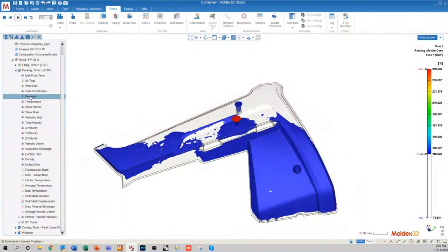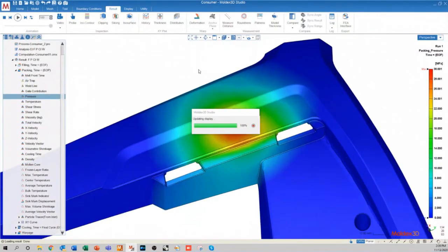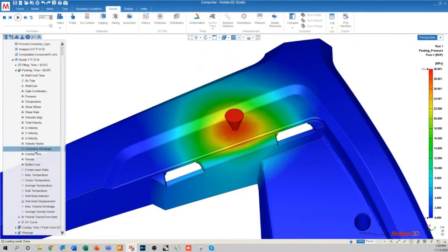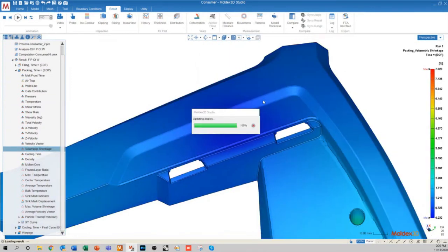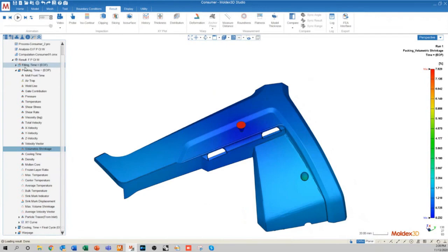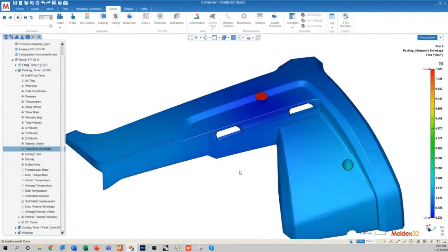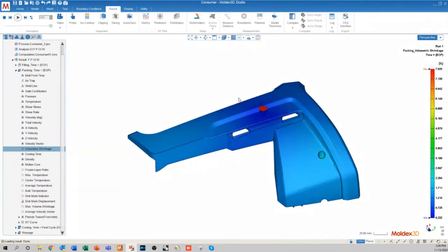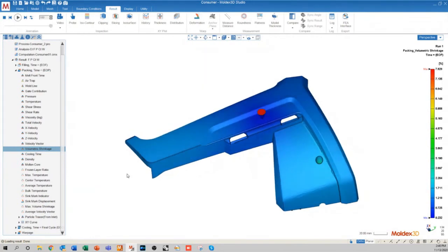Now, the amount of pressure concentration that we have on our gate is ultimately going to impact the amount of shrinkage that we're seeing in our part. And we're going to get into an effect called PVT in the cooling stage. And then PVT is going to explain a lot about why the volumetric shrinkage distribution is so important. But we can actually look in the filling and packing results, more importantly, the packing results. We can actually see what our distribution looks like before we allow the cooling to take effect.